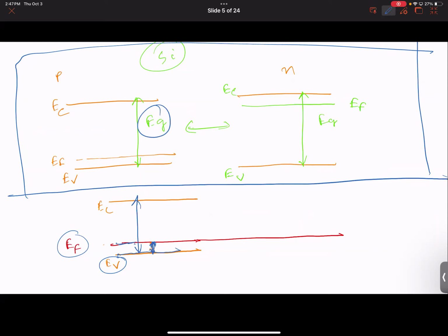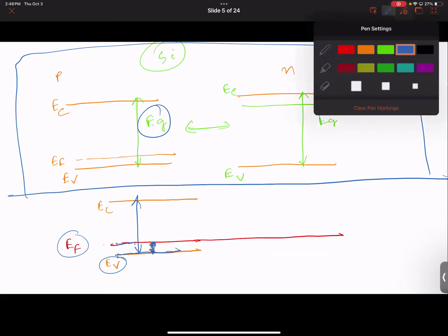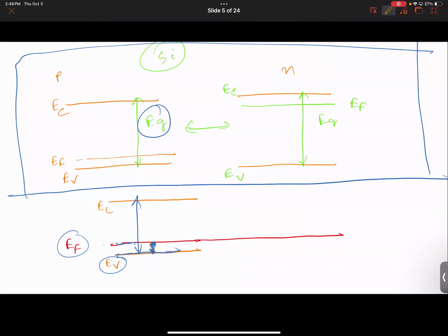All right. So when I was a student, we were asked to draw this at scale, not just sketching. So we had to calculate this first and then draw it and then draw the other one. Okay, next, how do I draw the N-type material? I start with the conduction band, because I can easily understand the separation between the Fermi level and conduction band, because that is determined by the doping concentration.